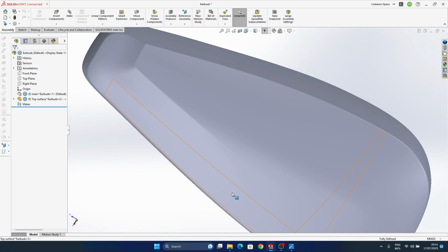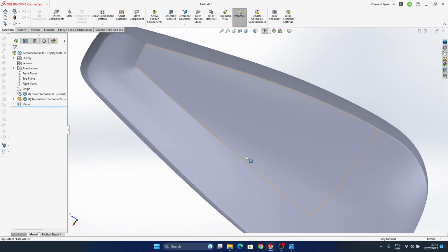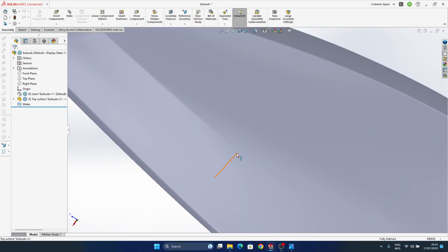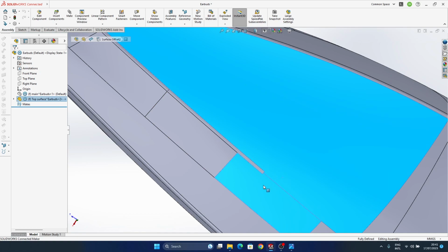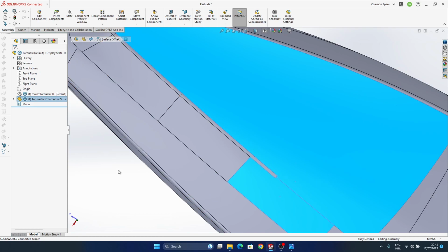So it looks like it works far better with boundary surfaces in curvature or whatever. I don't think it matters at the end, but the same principle is applied. So boundary surface up to whatever, up to this point in here, and only after that will these two surfaces in here be in continuity without having any sharp edge or anything like that, and the boundary surface will just transition smoothly.